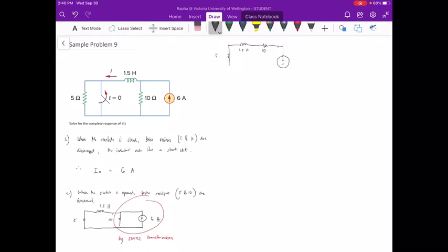Then our voltage source is simply equal to current times resistor. So we have 6 A times 10 ohms, we have 60 volts. So we obtained that by source transformation, which we have learned from the previous lesson. Since the 5 ohm and 10 ohm resistors are in series, we can add them in series, and our Req in series is equal to 15 ohms.